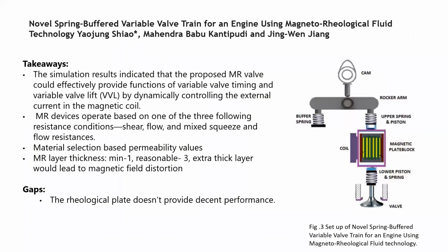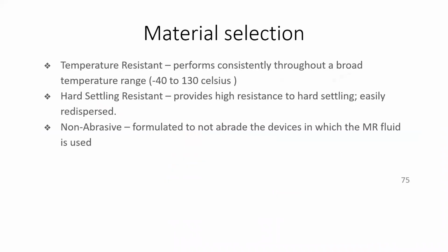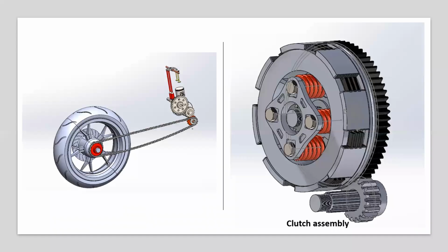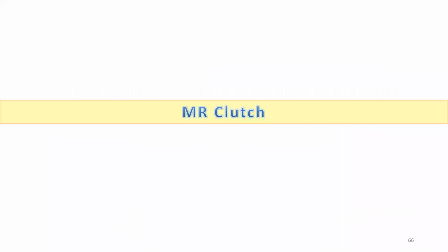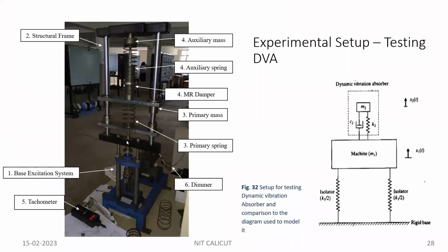Because we do not want to use such a smooth to-and-fro motion. We wanted it to vibrate violently, not very nicely. If you put a hydraulic cylinder, it will not vibrate because it moves very linearly and smoothly. But we want to show that it has to vibrate violently, and then we control it. That is why we have given this cam arrangement, so that it will have more instability.